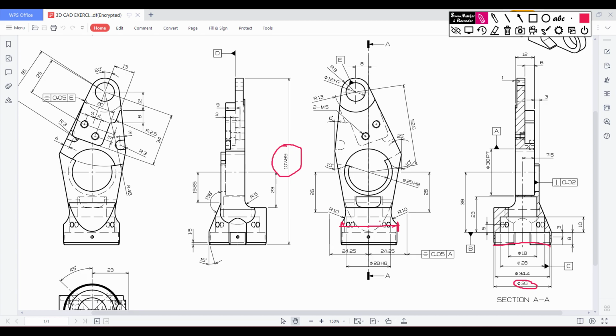So first, for drawing this portion I will select 2 points, one point is here and another point is here, and draw a dimension of 36 divided by 2 unit and 36 divided by 2 unit. Then I will draw two lines here and another line here. Then I will dimension from this upper point to here. I will dimension this to 107.89 unit.